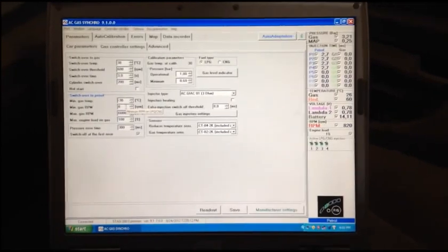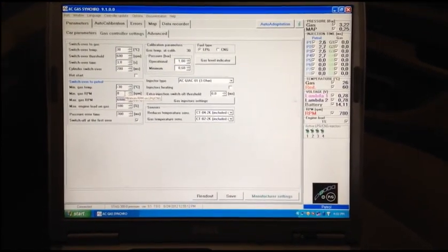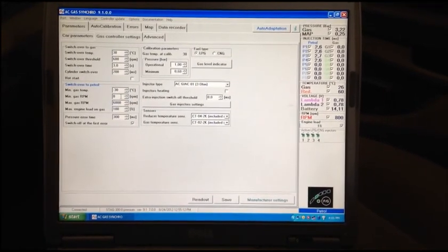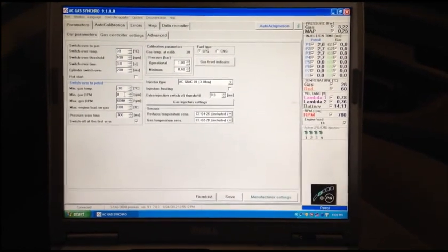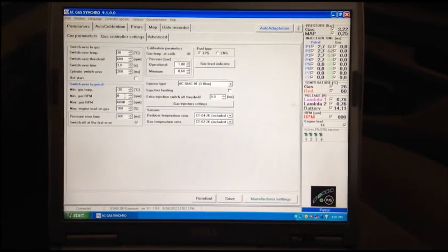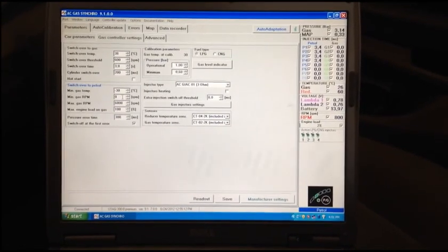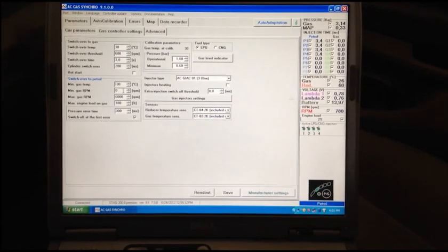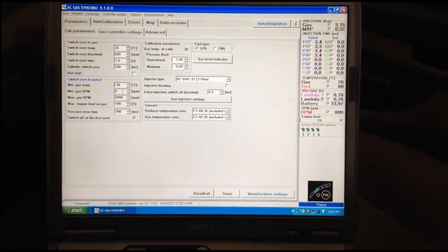I've only had one, an old pre-OBD F-150, where the mixture that the oxygen sensor was trying to achieve just wouldn't allow for a smooth idle. So when the truck came down to an idle, you could set this parameter to, say, 1,000 RPM, and anytime the RPM falls below that, it switches back over to gasoline.